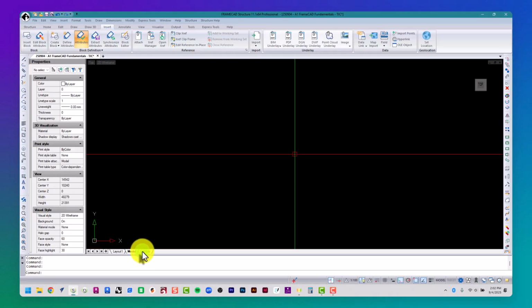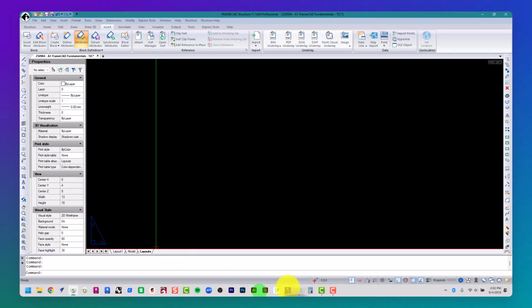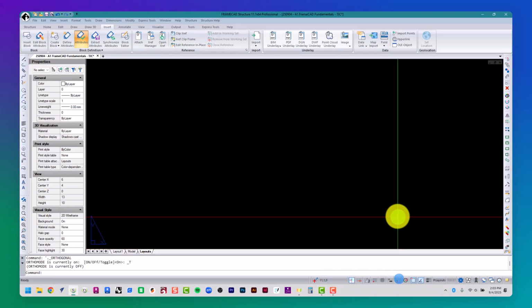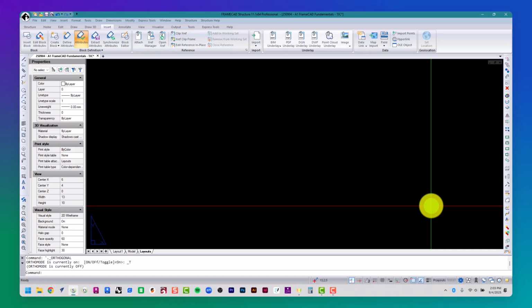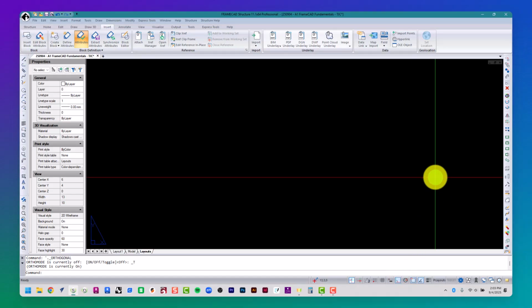And then down below here on the bottom right corner is what is called our status bar. It's got a lot of handy tools. These tools that I have turned on, I can see that they're enabled because they have this slight blue background to it. If I click on that, notice that it actually goes away. If I click it again, then it reappears. We have several different things, including being able to turn cursor mode on and off.